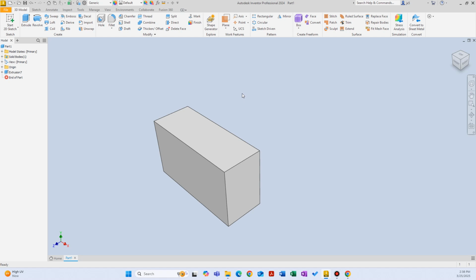Actually, there's another capability in Autodesk Inventor. Without looking at it, you can just draw a line. If you memorize where that command is, you can select that feature. For example, I know that in the right click menu, new sketch is in the south side of the center. So then I don't even have to look at it. I can hold down the right click and move down, and that's going to select new sketch. But that's very sensitive. I don't really recommend using it. I tried to use it before.